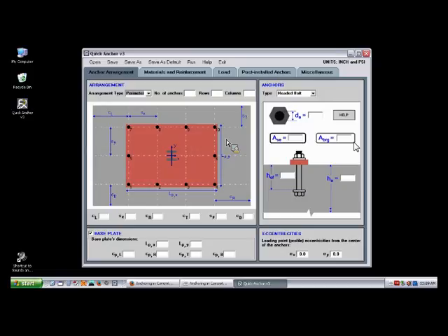So it will analyze the anchors for the imposed tension, imposed moments, imposed shear, torsion, etc., and see which anchors are resisting tension, which anchors are resisting shear, and include those anchors only to apply Appendix D provisions. And that is what is required by Appendix D. You do not consider anchors that are in compression in the group that you include in the Appendix D calculations. So this base plate is really required for that beam type flexure analysis, biaxial flexure analysis.